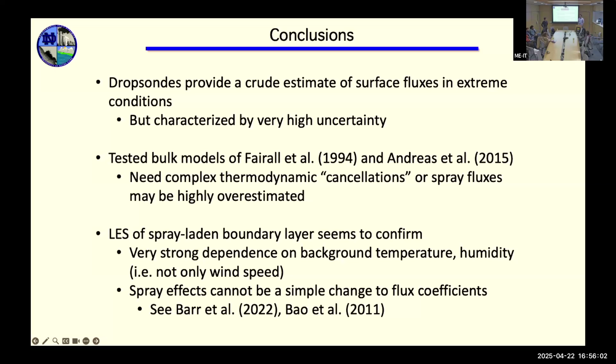So in an energy spectrum, your cutoff is way to the left, right? You're not resolving most of the inertial subrange. No, I think we are. You're resolving most of the inertial subrange at that Reynolds number? I guess what you could do, since you're using some type of eddy viscosity in your LES, is ask what's the ratio of the eddy viscosity to molecular viscosity? Yeah, it's gigantic. In fact, the molecular viscosity is not even in the code. It's not even close. It's 4 orders of magnitude different or something like this.